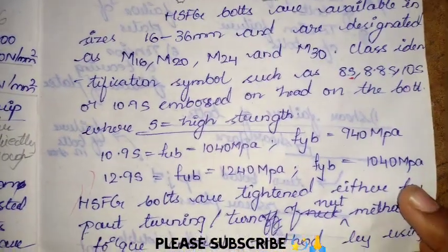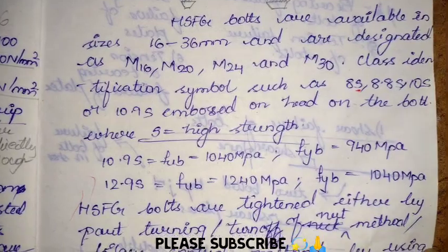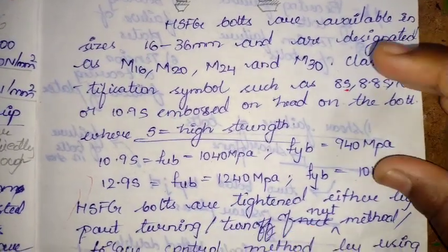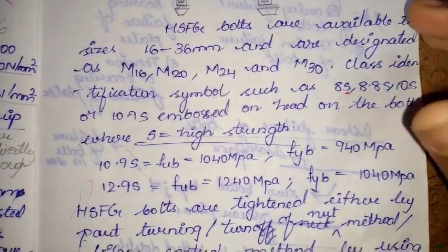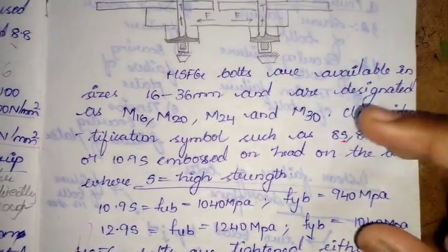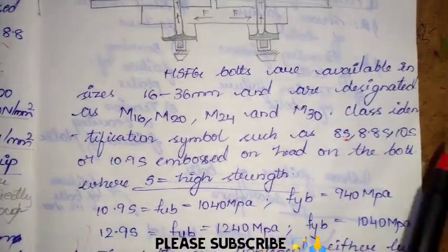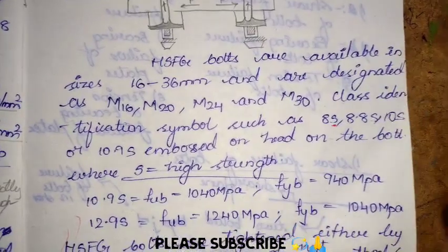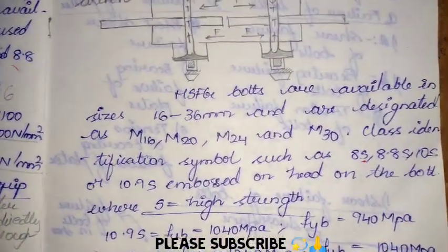So generally we have two types of bolts. The first one is the ordinary bolt and the second is the HSFG bolt. During the construction of bridges, dams or steel structures, we go with HSFG bolts for the primary members and for dynamic loads. But for secondary members, where only static loads have to be taken care of, we go with ordinary bolts.